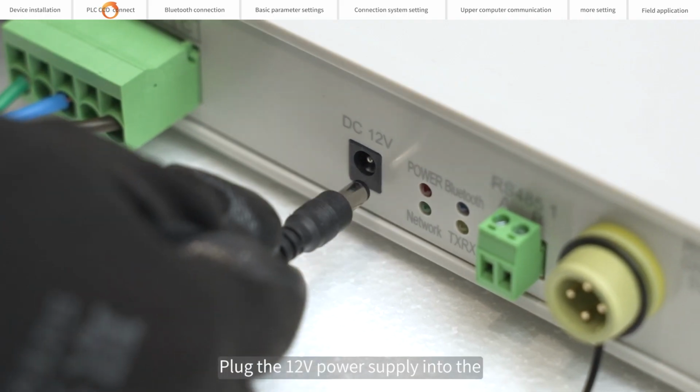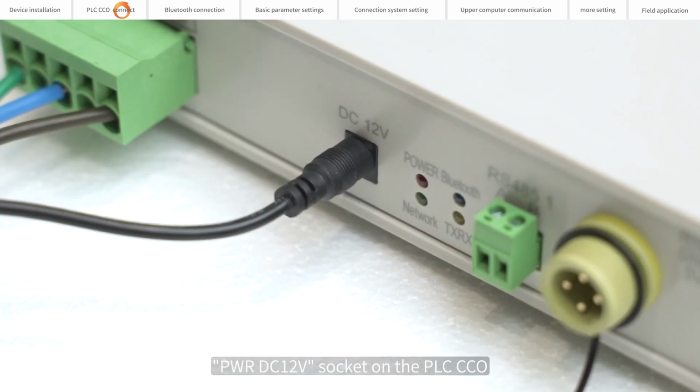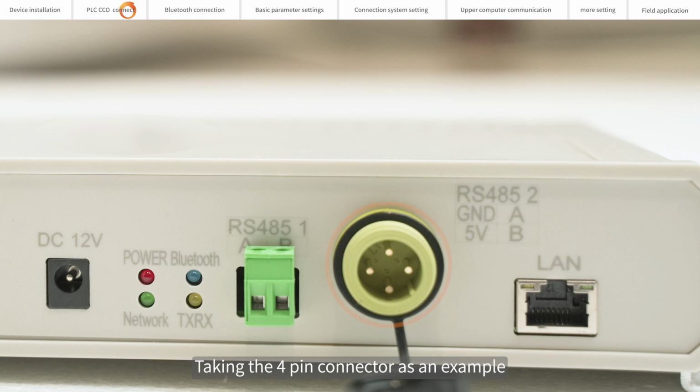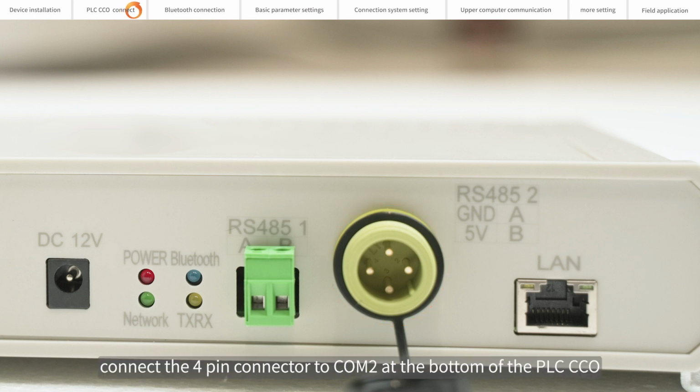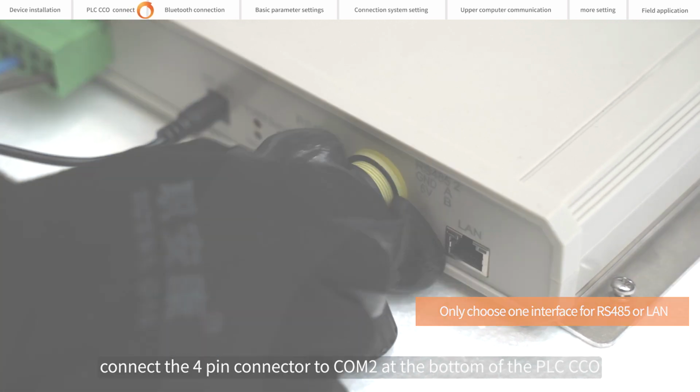Plug the 12V power supply into the PWR-DC12V socket on the PLC CCO. Taking the 4-pin connector as an example, connect the 4-pin connector to COM2 at the bottom of the PLC CCO.